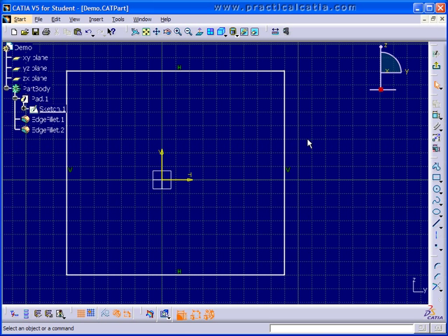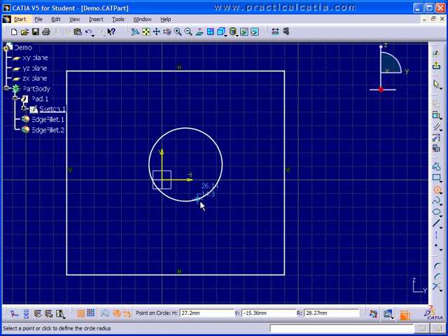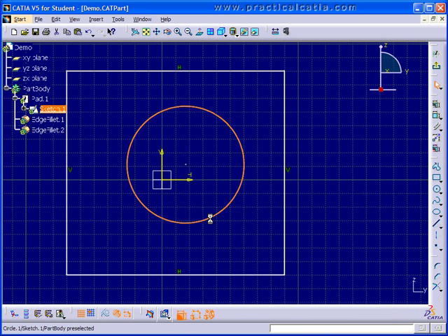Now what I want to do is just create a simple circle. And so to do that, I'm going to come over to the circle tool, and I'm just going to find anywhere here. Now where I click is going to be the center point of the circle. So I'm just going to click here, left mouse button, click, release the mouse button, pull, and click again, and a circle's created. Now later we're going to be talking about how you go about constraining this so that circle would have a specific size and location and so on and so forth. But for the demonstration that we're doing right now, that's not necessary.